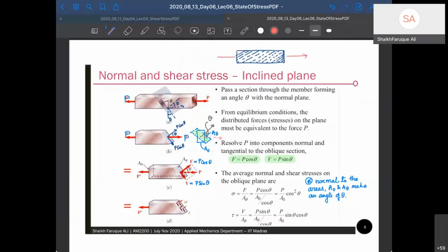So I have given an axial load P. And I'm very happy because its normal stress sigma along the zero axis, theta equal to 0, is lesser than my sigma allowed. We did this problem last class, right? I'm very happy that sigma at theta equal to 0 is lesser than sigma allowed. My design is over, pakka. I am very happy. Your client is very happy. Everybody is very happy. But suddenly, you see that there is a crack developing in the material along this direction.